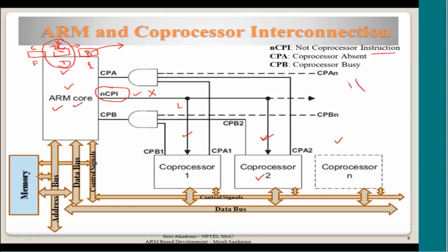See, you might have written code: if i is equal to some integer, equal to 1, then you do a floating point add, f add. If it is not equal to 1, you will continue with some other instruction, an ARM instruction or whatever it is. You don't want this f add to be done. So we are mixing the floating point instruction along with the normal control ARM instructions. So in that case, you should not allow the coprocessor to execute this instruction.